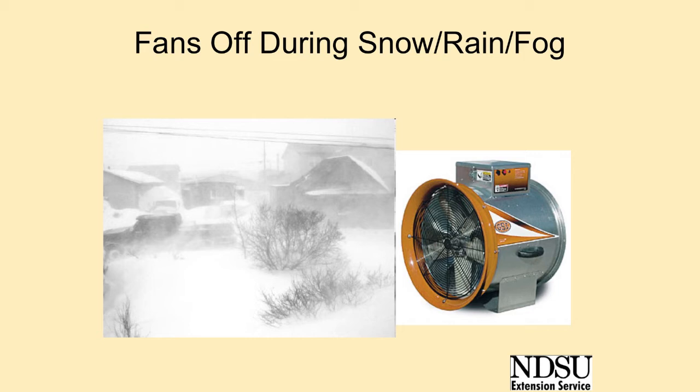A few hours of operation during a rain shower is not a concern, but operating the fan for many hours during fog or rain will move moisture into the bottom of the bin. Only the grain at the bottom of the bin will be wet if the fan is operated for a day during rain or fog. Normally, cooling grain with aeration will reduce the grain moisture content by about 1/4 to 1/3 percentage point.